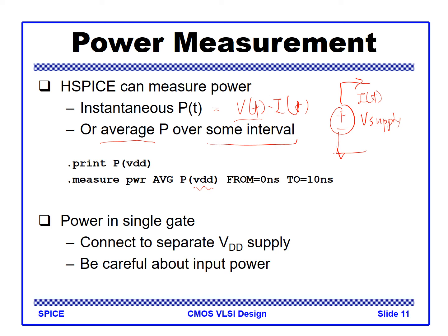If the circuit is periodic, like switching, then if you measure one period, the average power will be the same. If you measure 2 or 3 cycles, you get the same average value. But if you measure a non-integer multiple of the period, averaging to an arbitrary point, you will get the wrong average power.